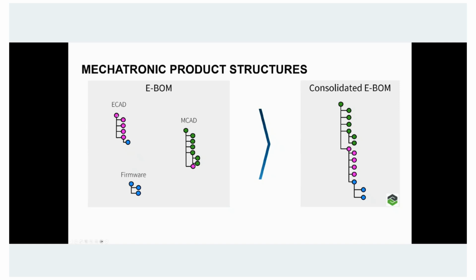And that's this guy right here, which is going to be showing right here. And when you put it all together, this is the BOM you're going to see: a consolidated engineering BOM inside of the PLM system with everything all connected together. Now, there are other ways to do it. It doesn't need to go like this. It could actually be a little bit more flat. There are different ways to configure it, but this is a nice view to really show the full structure of MCAD, ECAD, and software all together.